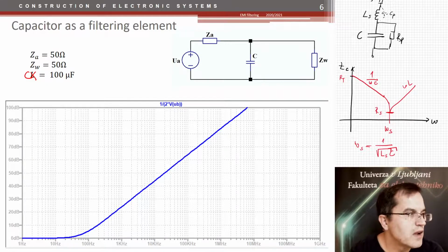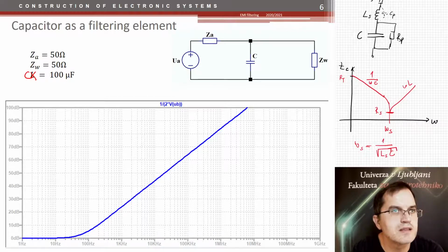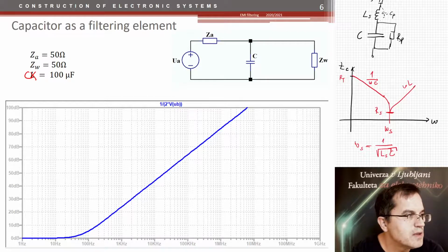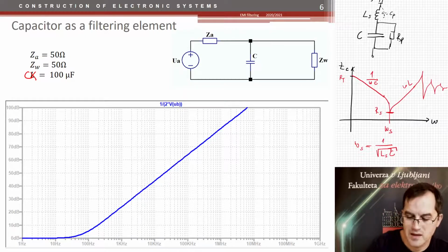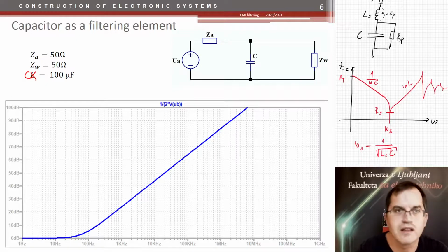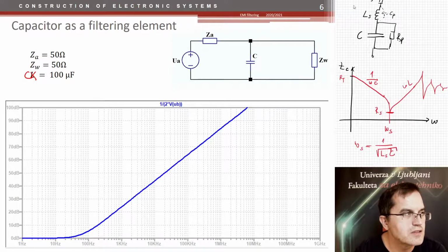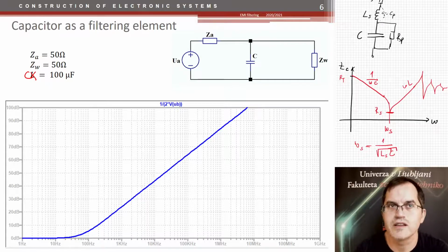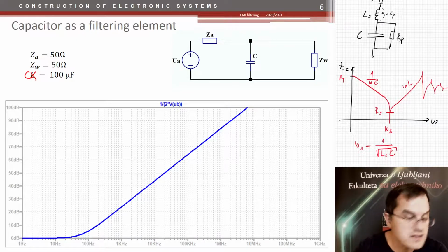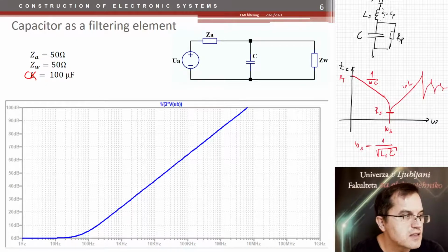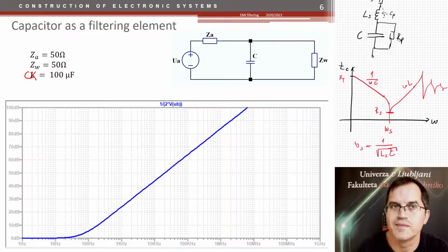Now omega L increases, and then we have the secondary effect where we have this CP starting to work, and the CP would then cause some high frequency oscillations. Not only one, because we have several non-ideality parameters that are influencing each other. So our capacitor is good as a capacitor till the omega S, then it starts to become a coil.